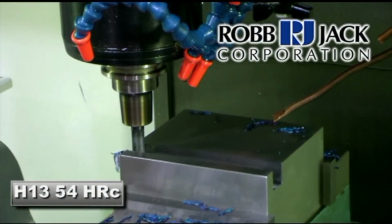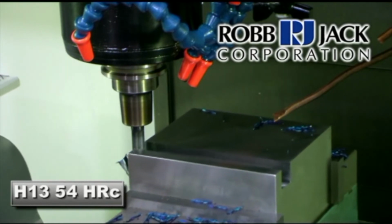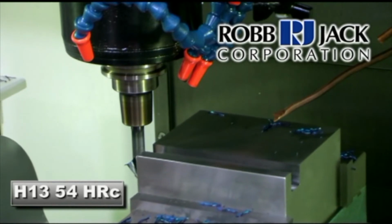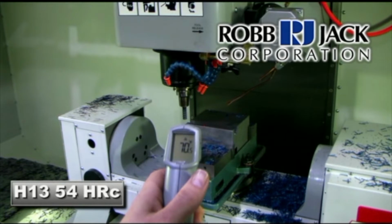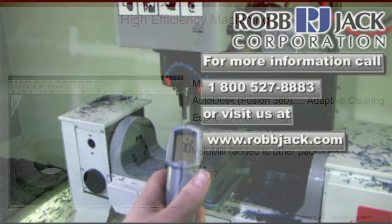And this works really well for titanium, for cobalt-chrome, nickel alloys, all those difficult to machine materials. When you do this type of light radial cut, the temperature of the tool was 72 degrees, the part was 70 degrees. And we were able to do that with the technique of that tool path.